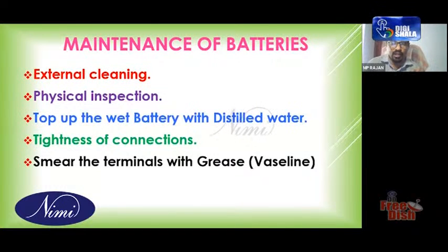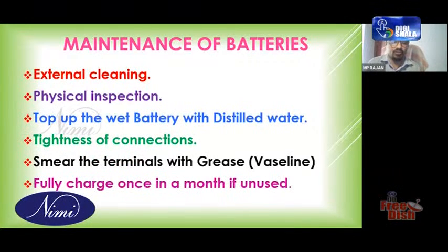So terminal को एक grease होती है, Vaseline, और Vaseline you can use. Jelly, petroleum jelly also you can use. You can smear, cover the terminal with a small amount of Vaseline in order to avoid the corrosion of the terminal. It will increase the conductivity also.